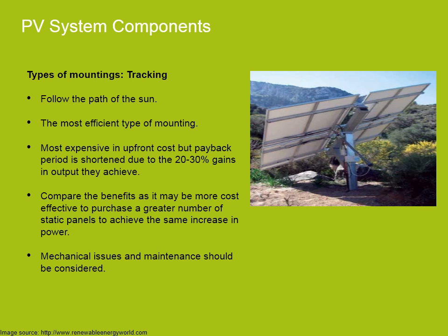However, in some instances, the 20 to 30% increase in efficiency can outweigh the capital expenditure. But you would have to complete a detailed cost analysis to ensure this, because generally at 2012 prices, one could instead buy 25% more panels, cheaper, and have the same increase in power with no mechanical failures to worry about.